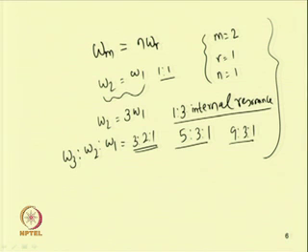That is why the system is said to resonate internally. In other words, internal resonance occurs in a system when the modal frequencies are commensurate. So one can have 1:1, 1:2, 1:3, or 1:2:3 or 3:2:1 internal resonance, depending on the frequency relation.